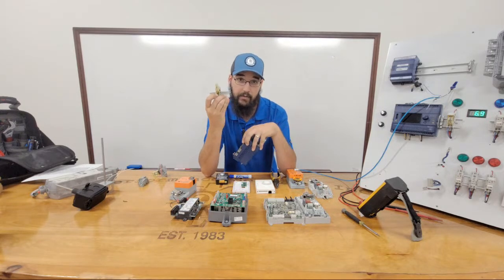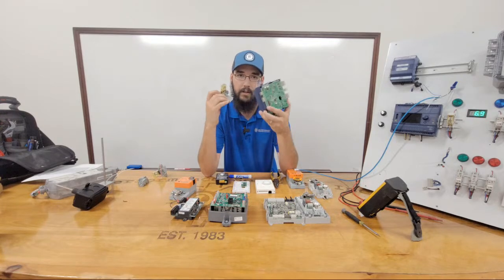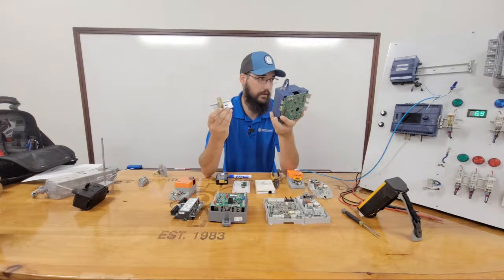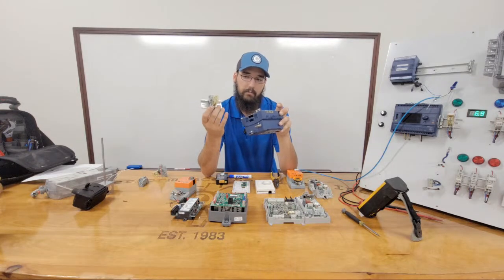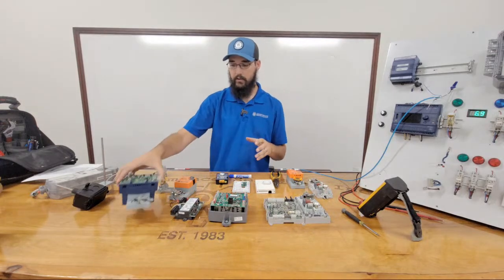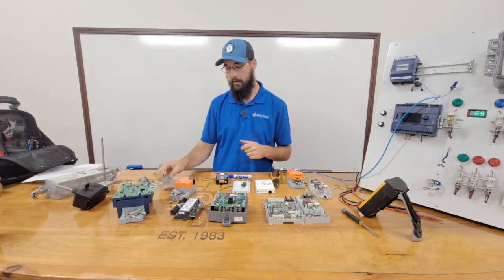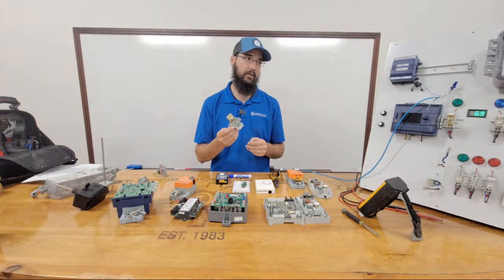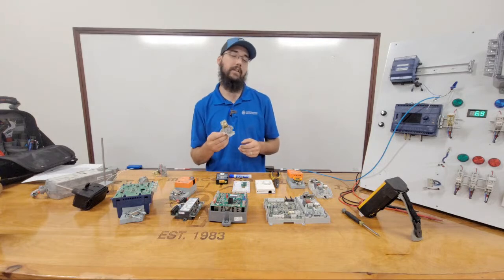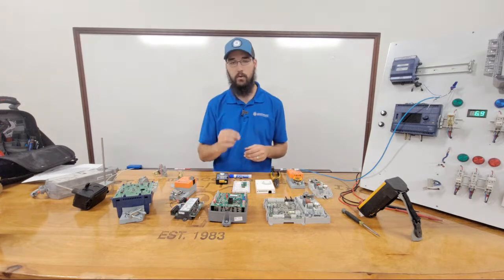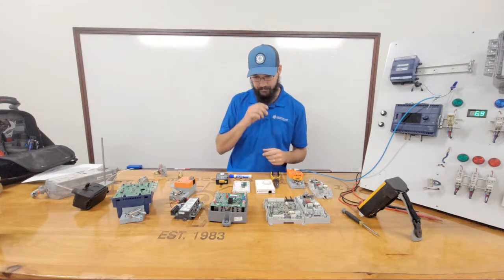These triacs need to feed through this coil. Feeding through this coil is not going to put enough load on those triacs to inevitably create a significant failure. They can handle that. I would not trust those triacs over a long period of time on anything other than this. And even having multiple of these run together, I don't even know that I would trust that. When I say that they are very minimal in the load they can handle, I really mean that.